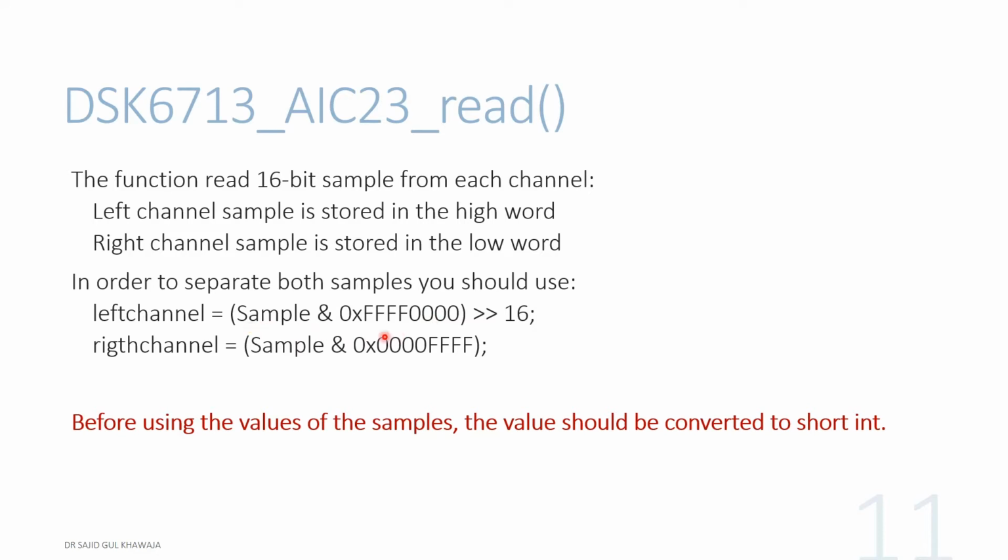This code written here specifies masking in C. Here we have masked the least significant 16 bits by 0. Once this constant and this sample are ANDed together, the least significant bits are turned to 0. Once that's done, we'll simply shift this answer by 16, so that the most significant bits are now placed in the lower 16 half of the answer.